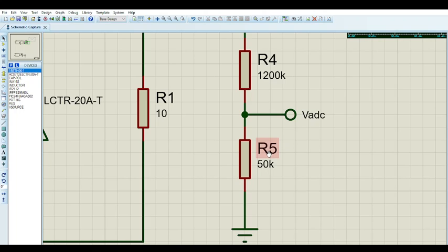Like, I mean a lot, like 10 times less than quarter watt, just to be safe. Because once it starts getting close to quarter watt, they start to feel warm a bit, and once the resistors start to feel warm, that's a huge problem. You do not want that. That's a bad time for control.